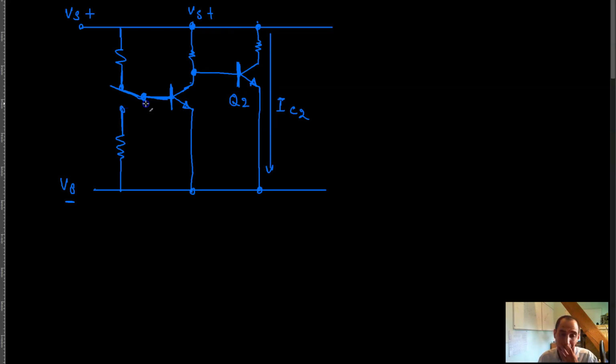And then on the other hand, if this switch is tied to the positive rail, then the current goes through this resistor, to the base, to the emitter, to the ground, which means that the transistor is turned on, of course depending on the values of these resistors. The transistor is turned on, meaning that there is collector-emitter current going, meaning that the current essentially goes through this load and goes to the ground, which means that the current doesn't go this way to this transistor, and this transistor is turned off, and as a result this load over here doesn't really get any current because it's not tied to ground, right?